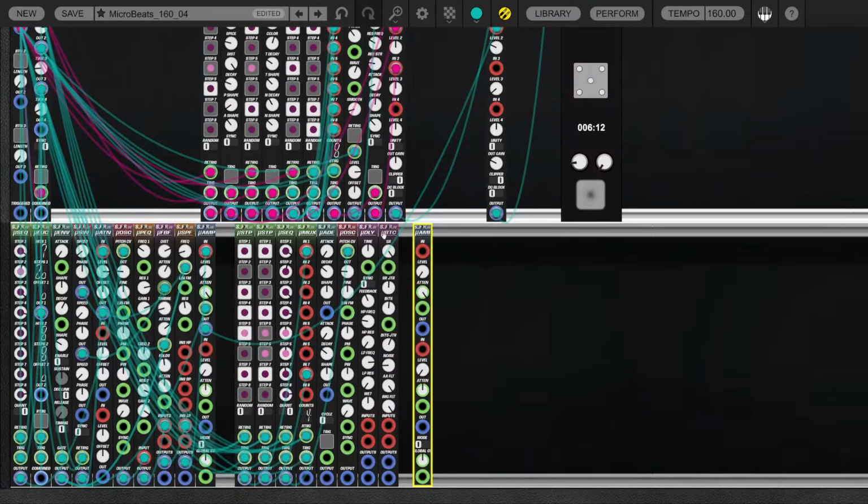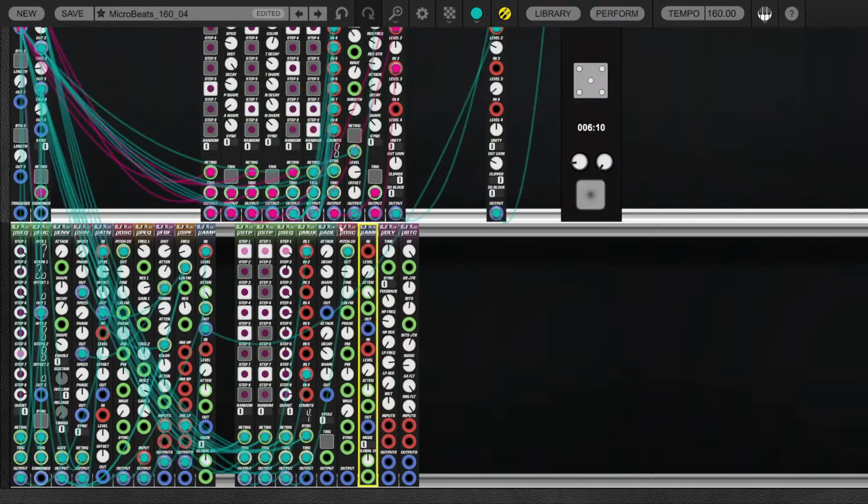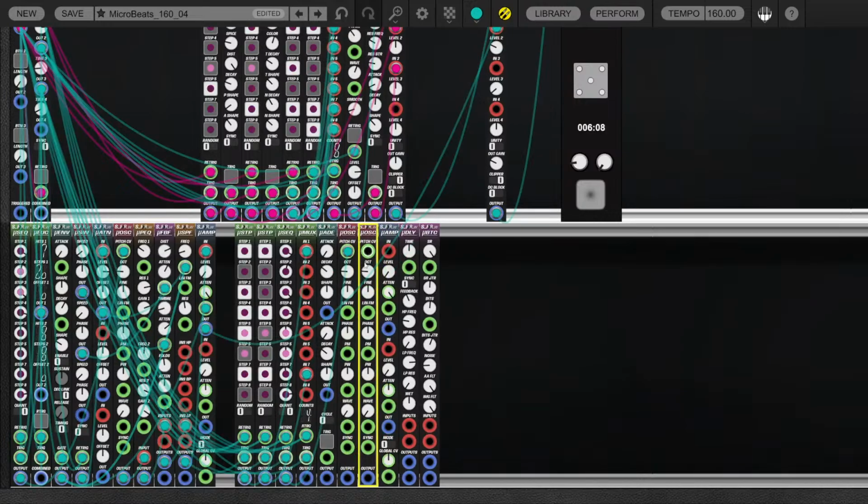We need an amplifier. Let's put all of that here. Let's go with a second oscillator. Then we will connect the multiplexer output to the trigger input of the AD envelope. And this will go to the first amplifier channel and the second amplifier channel. And now we have 2 oscillator setups, so we already know it's going to be an FM patch. First oscillator modulator, phase modulates the second oscillator carrier.